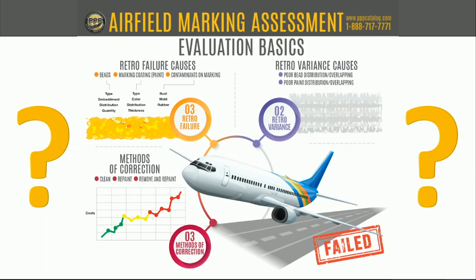The best chance, and we have a little bit of data on this that's coming in over the last few years, the best way to combat that and to make your markings last longer in those regions is to essentially remove your markings back down at the pavement and put a very good application initially on the surface: uniformity, embedment, all those things. Then you have a much better chance of surviving snowplows.